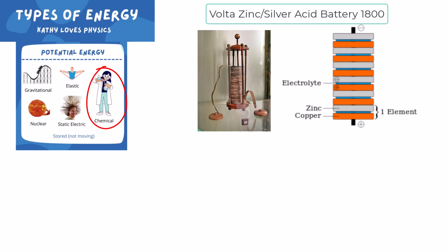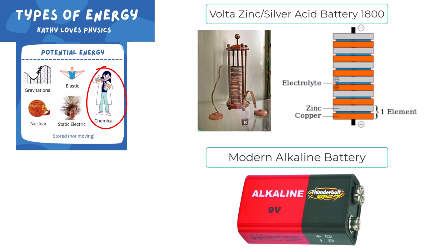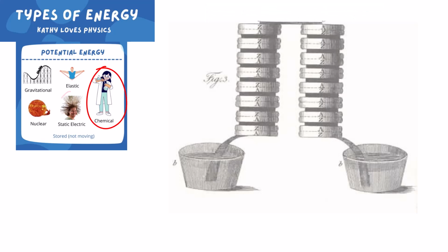Battery cells are very simple. They have 2 different metals in either a strong acid or a strong antacid, or alkaline. And the chemical reaction happens until the negative electrode has too many electrons and the positive electrode has too many positive ions, or atoms missing an electron. These charges arrange on the surfaces of the metal until the potential energy of the charges on the plates equals the chemical potential energy of the acid or antacid.